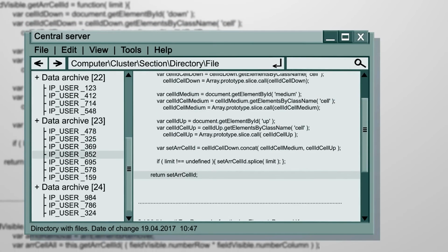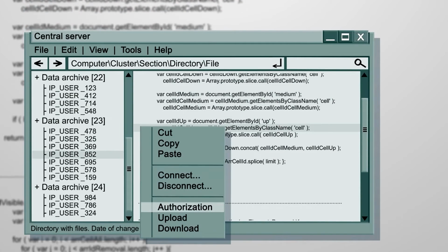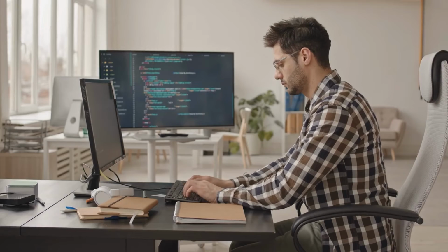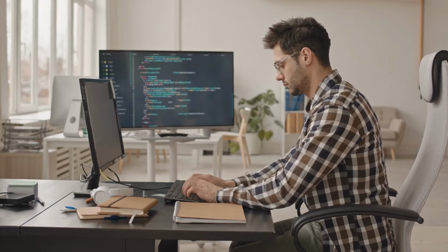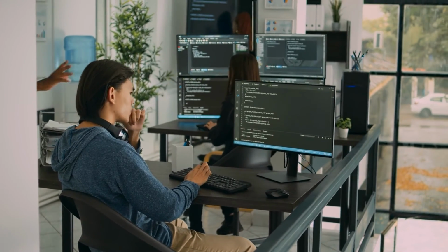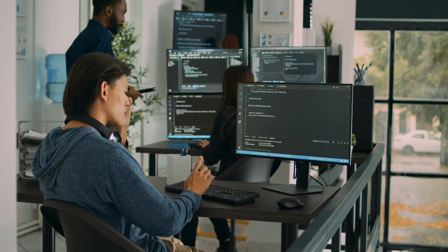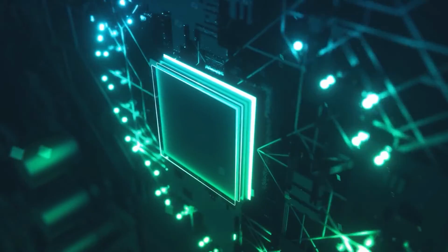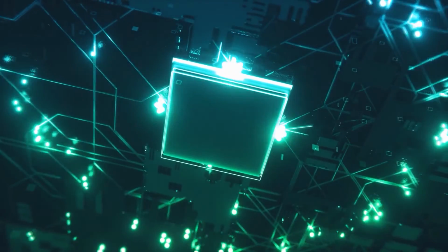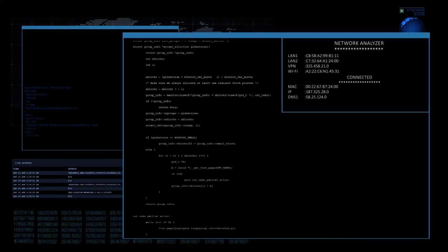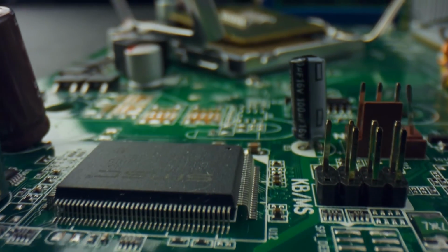If you have an operating system, there are still electrical engineers that can do all types of programming, but since you're moving away from requiring a solid understanding of the hardware, you tend to get more into the realm of computer science and programmers than electrical engineers. Just keep that in mind. If your product is using a microprocessor with an operating system, then the requirements for the firmware are going to be quite a bit different than if you're running a microcontroller without an operating system.